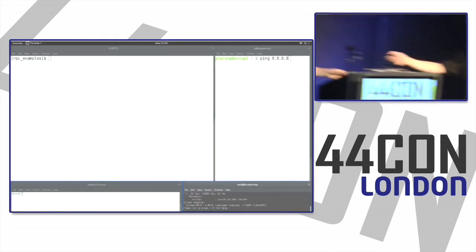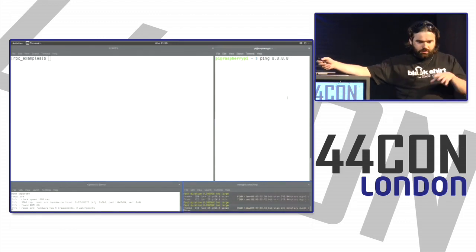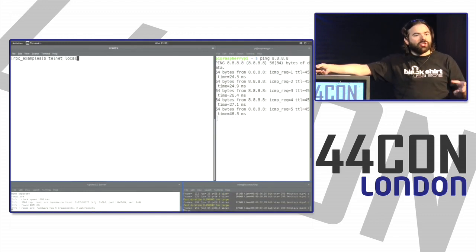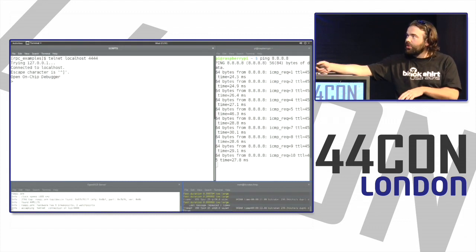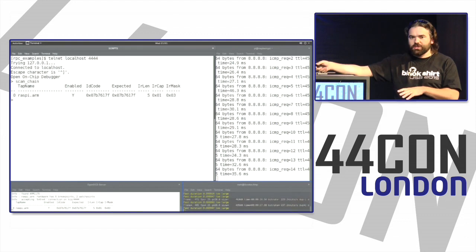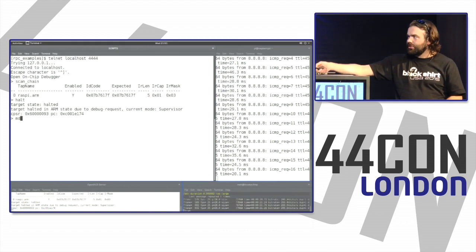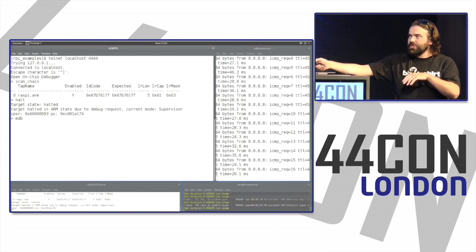And so when we run OpenOCD over here, OpenOCD is running on our host PC, our attack PC. It's running the server that is controlling the JTAG adapter, which is what is creating the TDI, TDO, TMS, TCK signals. There's this client server interface, so we open up another window and access that server as a client. So just so you're clear, this is telnetting into the Raspberry Pi. These are both running on the local system using utilities to manipulate via JTAG.